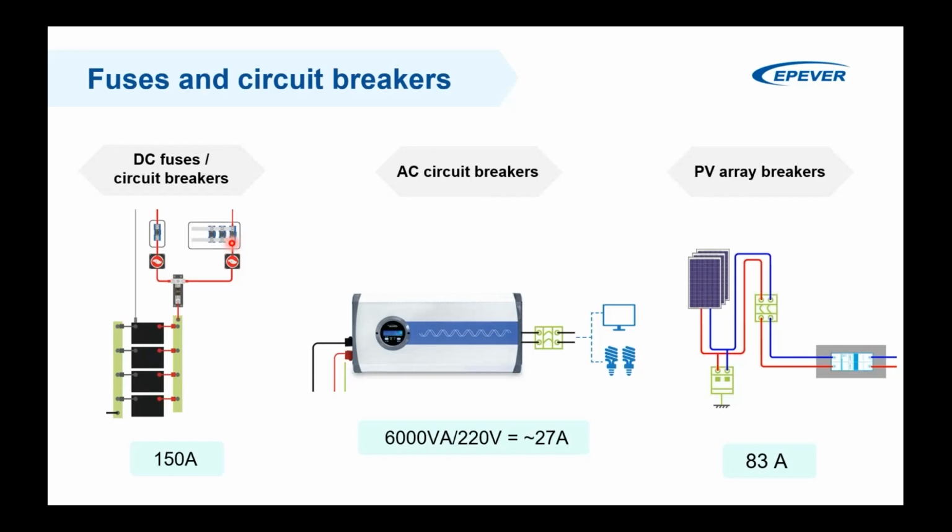If the consumer develops a fault in its internal circuits, for example, consider that one of the consumers directly connected to the battery has a short circuit fault, then it's a disaster. It can even melt down the cables and all the terminals in the system, because you have a huge, massive amount of current with a considerable amount of voltage. This is high power, and it can melt your cables down.